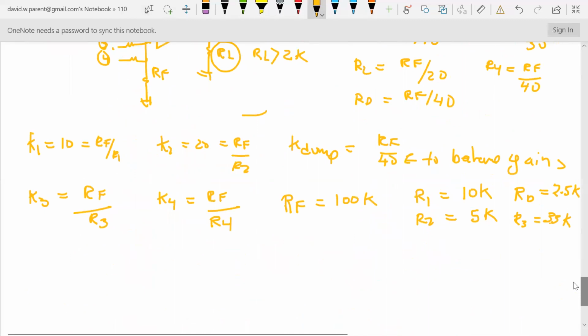So conceivably, if I wanted this to be 5, I'll make that 200K. Or if I wanted it to be 10, I would double it again, and then everything would be reasonable. I wouldn't have to worry about overloading it. What I said just there, that's the future, not this homework. But when you're in lab and it's not working, even in simulation, those op-amp models will break down when you're trying to drive too much current through them. Okay?